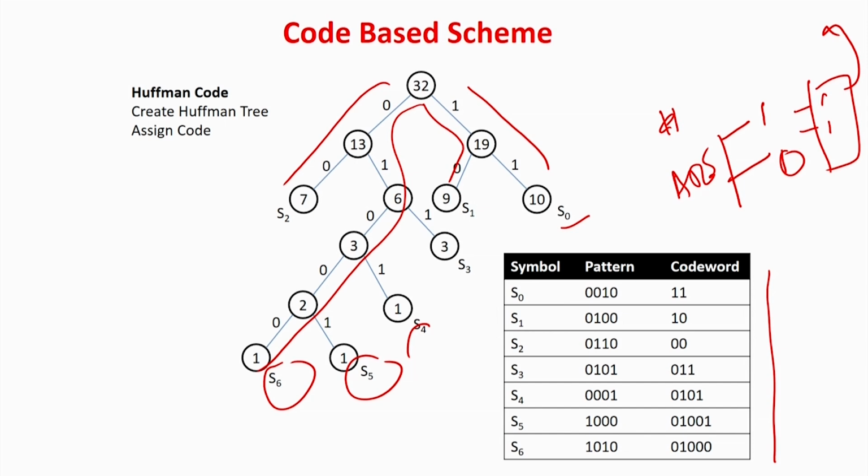I am going to give you an example of a modification people have thought of. There are many patterns which are low frequency and occur very rarely, but if you are still using them for encoding, then your decompressor circuit may be large. So one option is that I will take only the most frequent code words and code them using, in this case, Huffman code, and the others I will pass directly, so that my decompressor circuit is not that large in size or does not take more area. Only for the rare occurring patterns you require more width of the ATE, for others you do not. So let once in a blue moon one pattern be applied; for that I will take all the channels of the ATE rather than making the decompressor circuit too large.